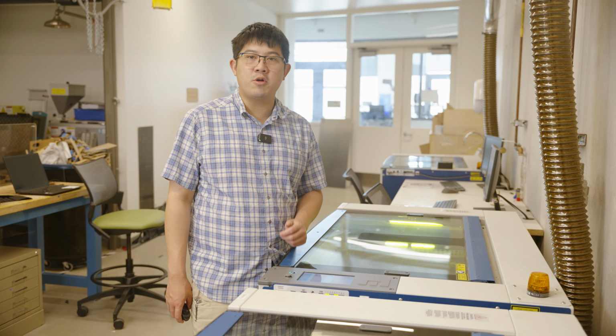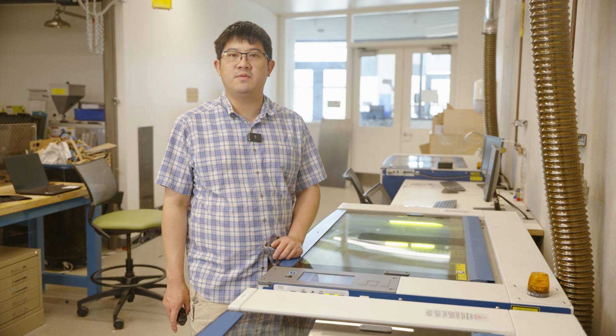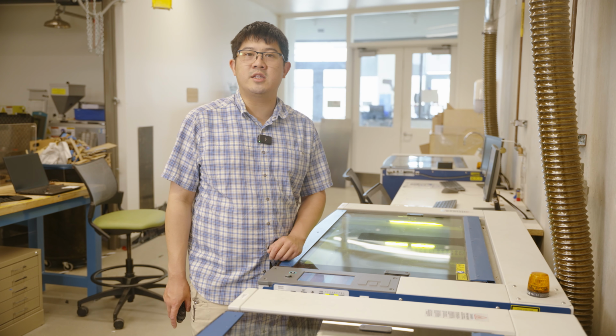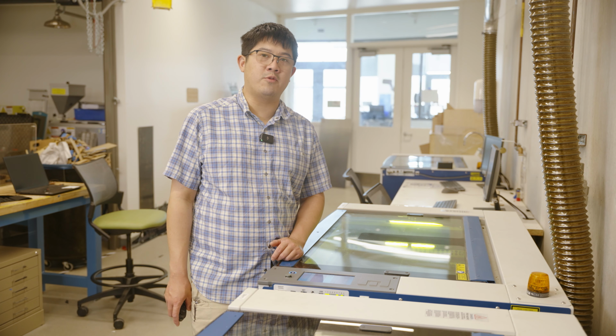For many materials, you'll see smoke. In some cases, you may even see the smoke erupt into a small flame that follows the laser cutter. These are normal responses to the laser speed. The important thing to notice is if the flame grows or spreads to the material itself. If you have any doubts or concerns, you can always hit the pause button. The fire should immediately stop when the laser does. And you can ask one of our staff members to double check your work for you.